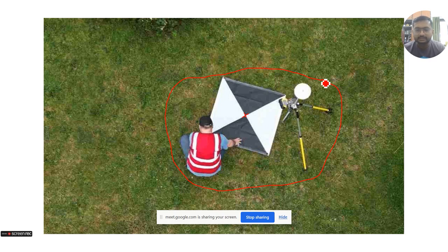We can take help of another georeferenced image and do image to image registration. But if we do not have any georeferenced image, we can take structures which are permanent in nature, such as a temple, church, mosque, the starting location of a bridge, or some old building that has been there for a long time. That will not change in the nearby future, so those points we can take as a GCP.